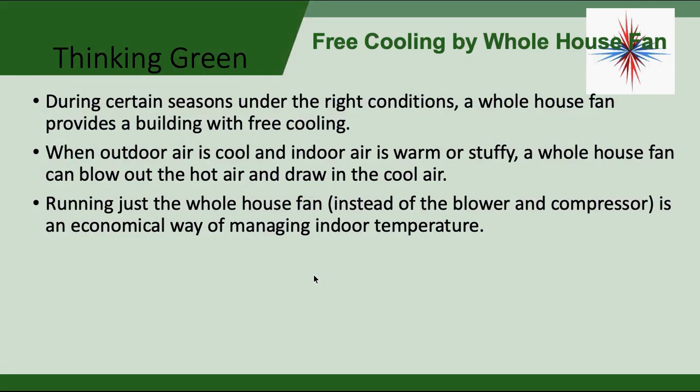In a commercial building on a nice cool outside day, the amount of heat generated inside the building by people and equipment may heat that building up over outside temperature. If I still have a nice, cool, non-humid day outside, I'm going to open up a whole bunch of dampers. I'm not going to run the compressor, and I'm going to pull outside air into the ductwork and exhaust that hot air.